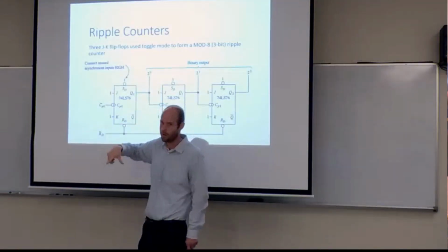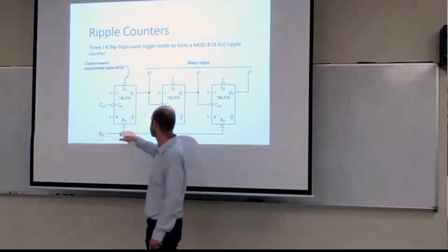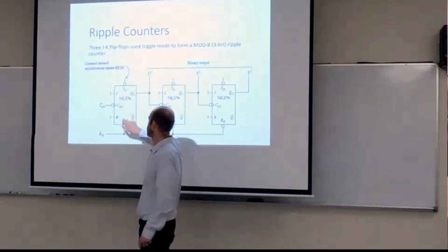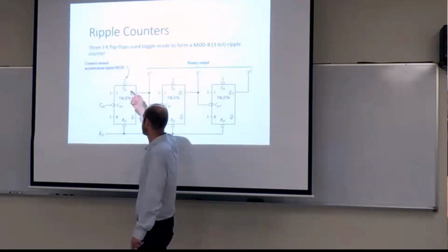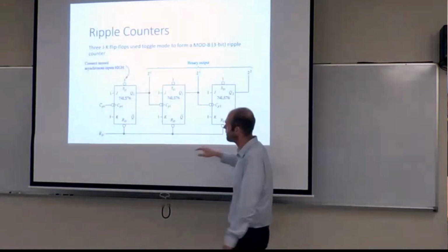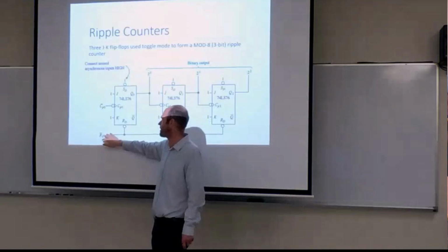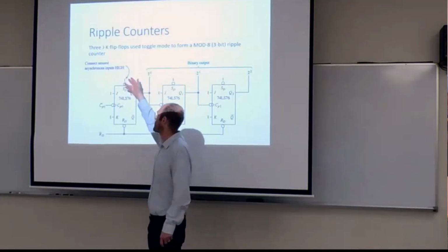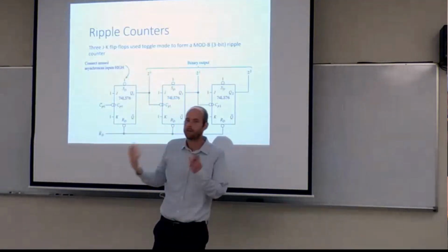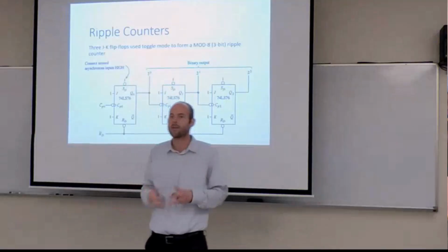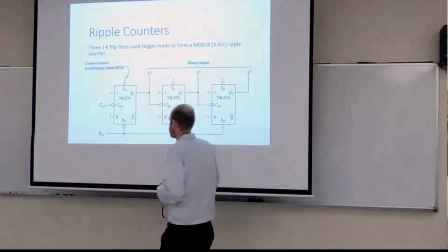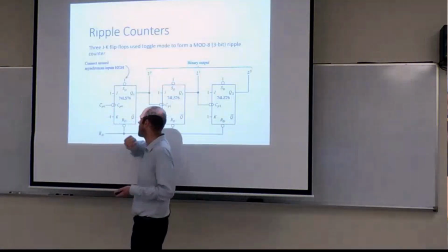It's active low. So the reset and the set are active low, so they're essentially being tied to 1. The reset has a mechanism so you can reset it manually if you want. They're asynchronous set and reset, so you're not changing the bits outside of the timing of the clock.